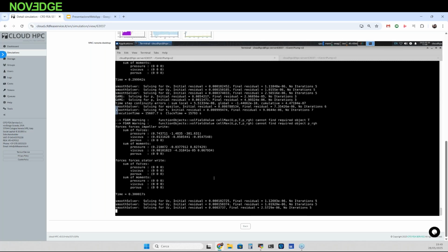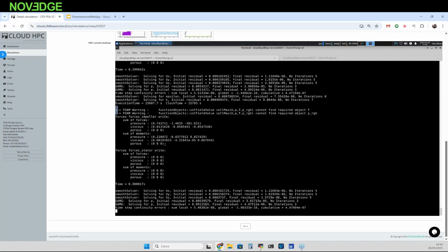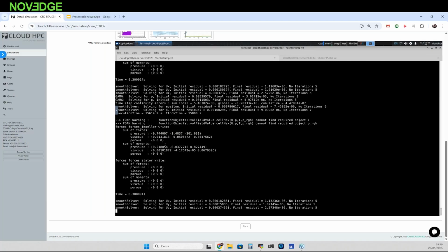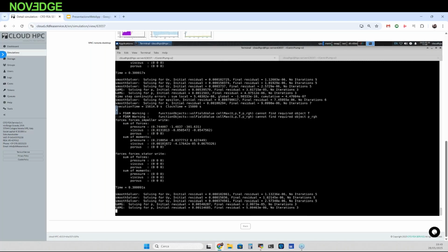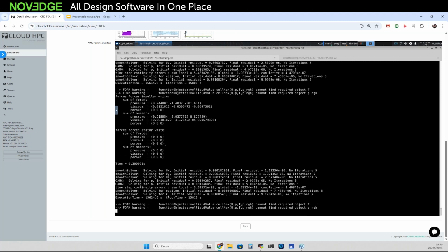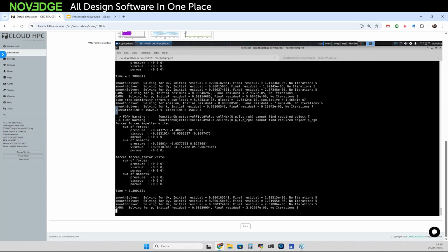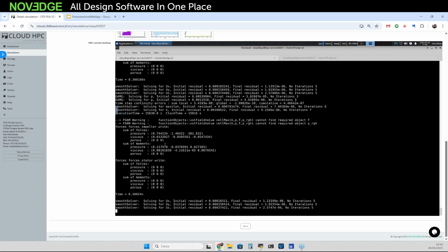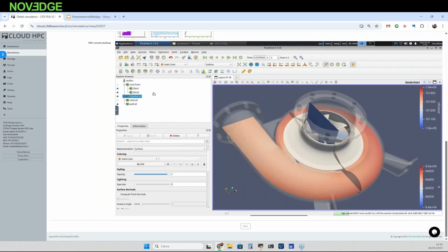and I can get information on what OpenFOAM is actually doing. I can monitor forces, torque, or any fluid dynamic quantities that OpenFOAM allows me to track in order to understand the evolution of the simulation, evaluate the absorbed power, evaluate the head generated by the pump, evaluate any sort of data that comes from this particular simulation. And obviously I can use